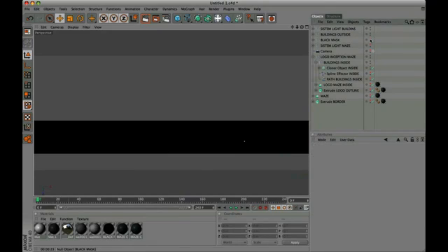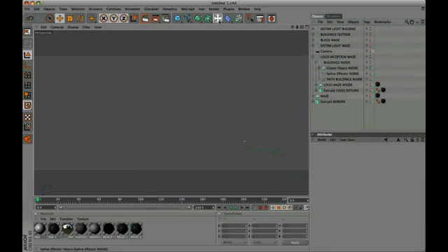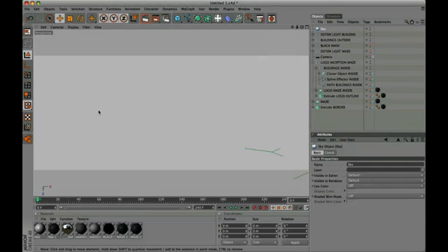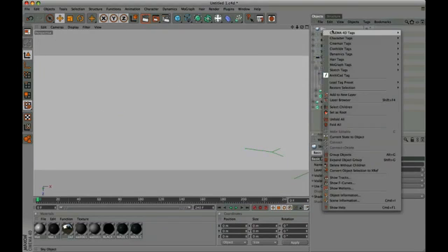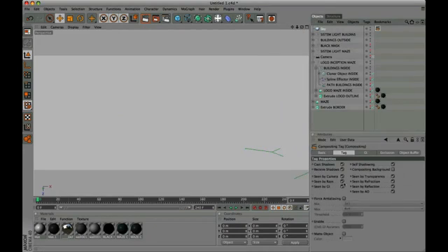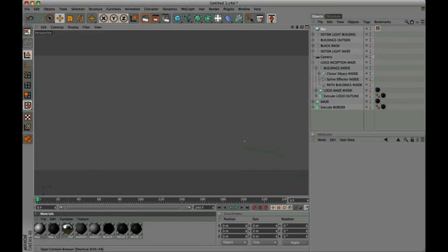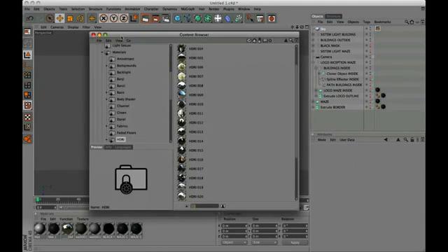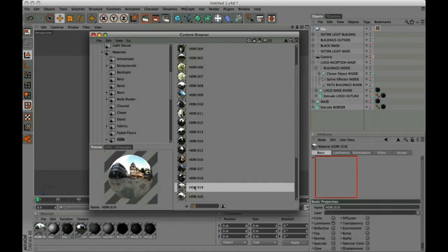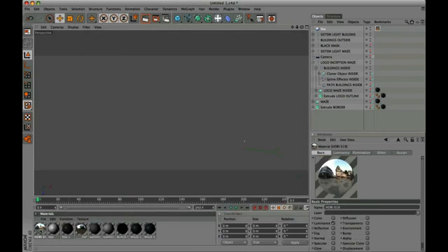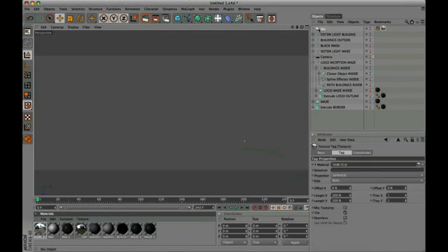Okay, to improve the reflection of our buildings, we insert a sky object in the scene. We apply a compositing tag, disable seen by camera. Set the HDRI 019 material, already in the Cinema 4D library. Insert the material on our sky object, on Luminance panel.